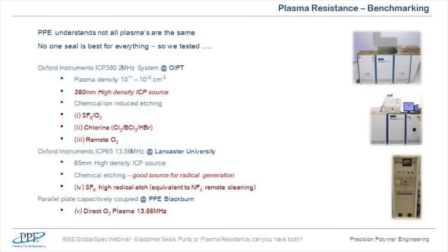Well, we have done a lot of plasma exposure tests. We have picked some of the most common chemistries used in semiconductor processes. We picked five different chemistries and different plasma sources, and exposed our and competitor O-rings directly to the plasma and measured the erosion rate.